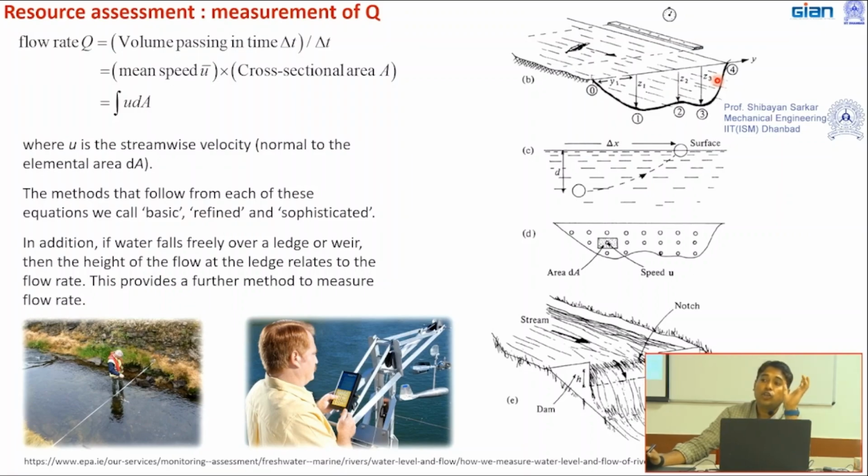Another technique: you can download satellite data. If you cannot approach this area initially, you want to do it remotely. SRTM data, Shuttle Radar Topography Mission data, I will show you a bit later. That data is available on the internet throughout the world.